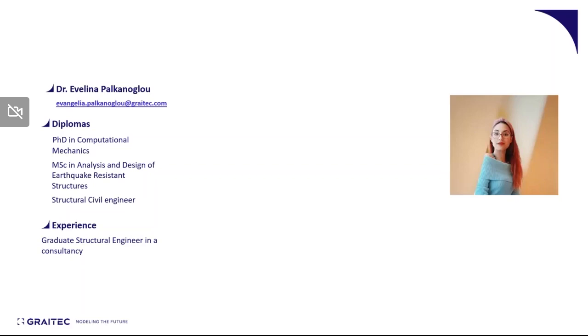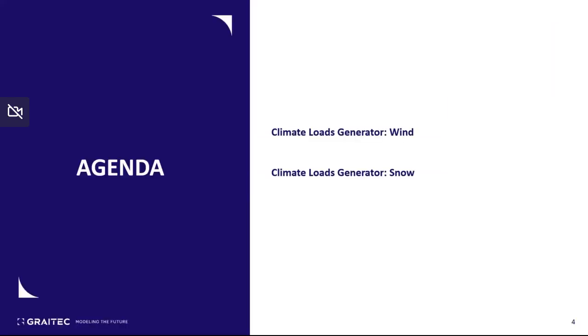Today we will see how to use the climate generator in advanced design in order to create and calculate the climate loads such as wind and snow quickly, effectively and efficiently. So the agenda for today is the climate load generator for wind and snow.